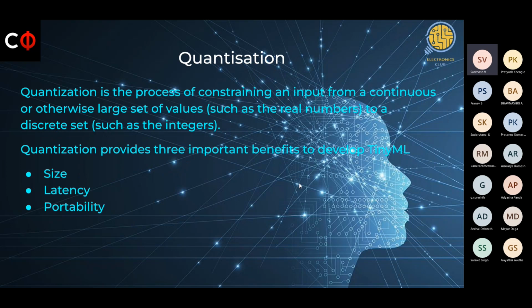Quantization is like this: after training, the model has weights and biases. These weights and biases may not necessarily be integers. So what happens if they are not integers? Well, floating point operations are always lengthy, and the data will also become lengthy. So your microcontroller sometimes cannot handle so many calculations, and it tends to slow down a lot. So what we do is quantization.